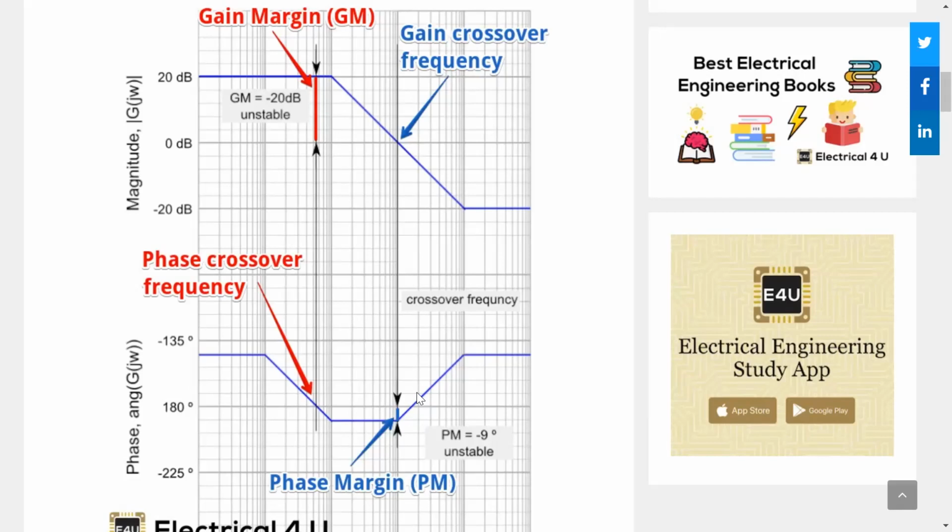What we say here is, as long as the controller does not shift us by more than -9 degrees, we're good. So notice we here have -135, -180, -225. It's just a matter of how you count. But okay, so -9 degrees, big problems. If it shifts us by +9, no problem, and so on.